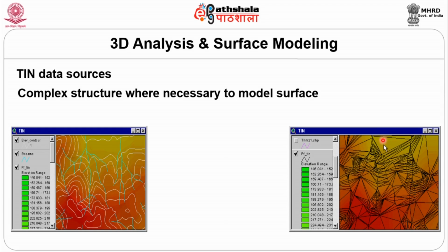So these are all relatively flat terrain when compared to the surroundings. Coming back to this, we find that this entire area, zone or part is divided into n number of triangles. The total area is divided into triangles, and that is used as one of the inputs for TIN generation.